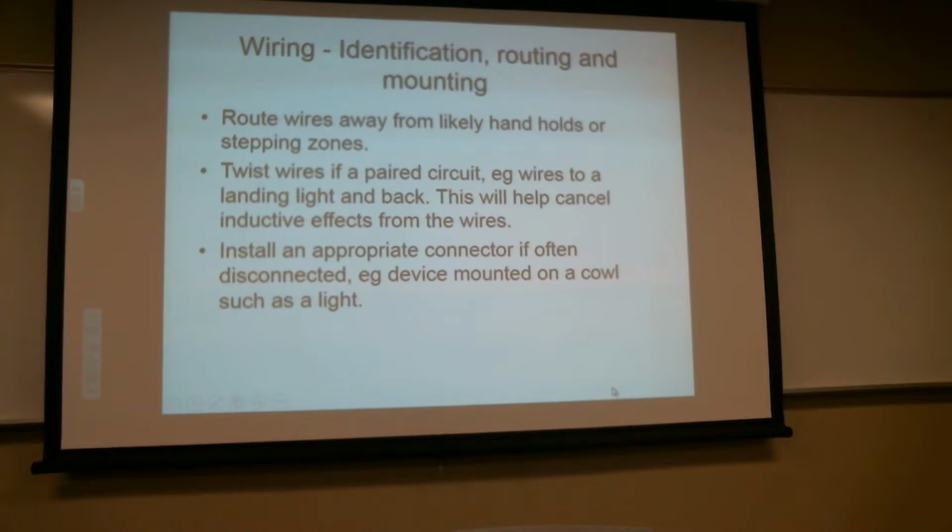The problem is you don't know how much current that shielding is really designed for, do you? You can calculate how much current the center conductor was designed for because they gave you a value for that. They gave you 22 gauge or 24 gauge. But they don't tell you what the gauge is of the shielding surrounding it. And so there may be a voltage drop coming back.